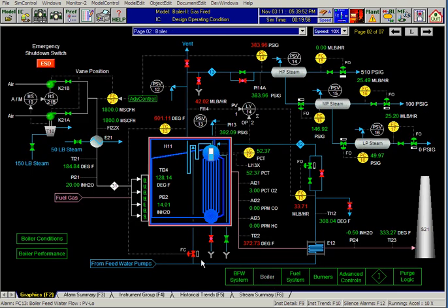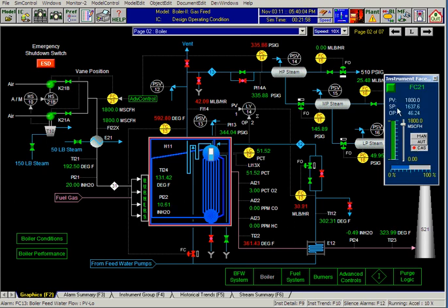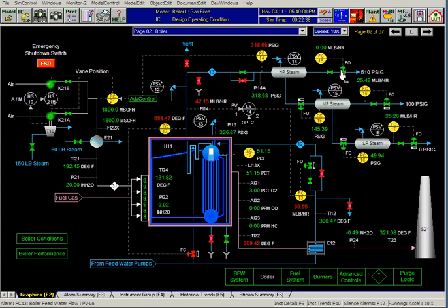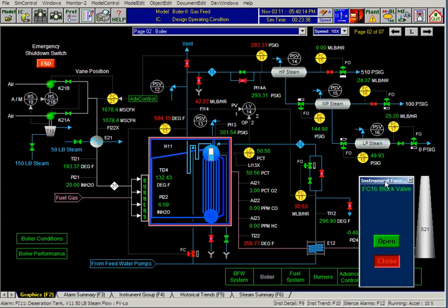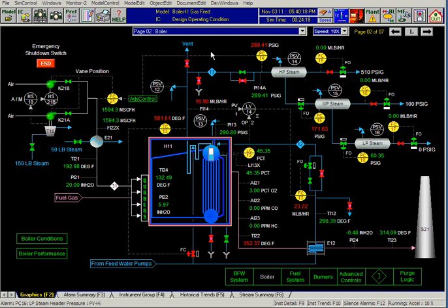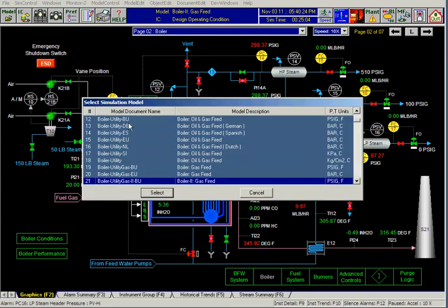Okay, sound that you're hearing at the moment is probably the backup fan came up because the boiler tripped, the pressure is going down, and it's basically saying I need more fuel, more air. Air is basically maxed out, so that's why the second backup fan started. And actually, one of the first things I should have done was I should have isolated these steam to demand, because otherwise, this will just depressurize to atmospheric pressure. Okay, so that's a brief overview.